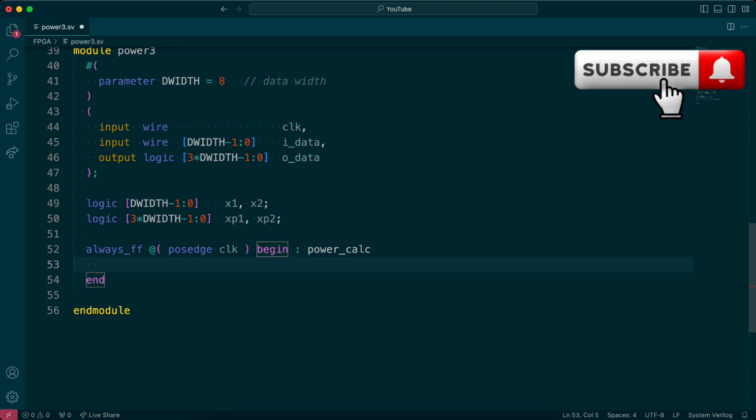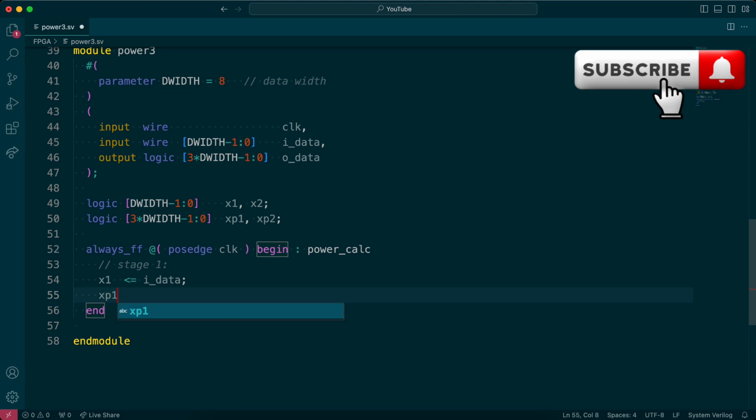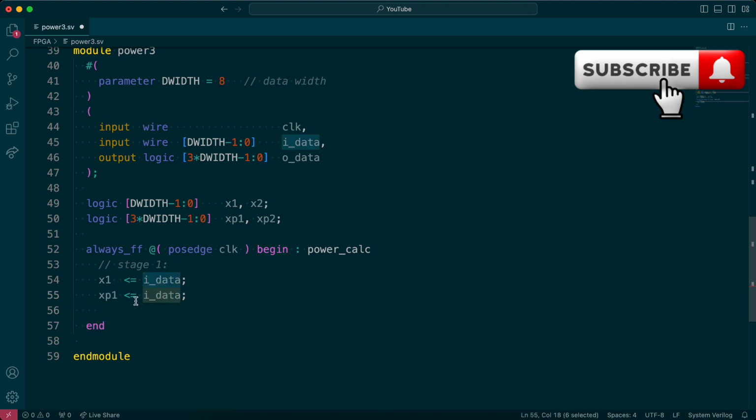So all I want to do here is to go in stage 1. It's a pipeline design. It has different stages. In the first stage, I want to go x1 is iData. So it gets the value of the iData, and the next clock the value is assigned. And then I can go xp1, that's also iData. Note that xp1 and iData don't have the same data width.